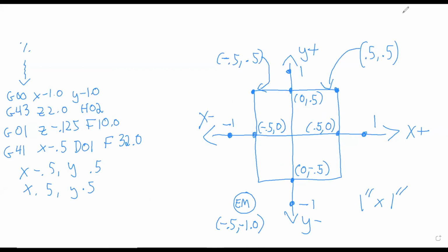All right, so moving forward on using G41 and G42. The last slide mentioned how the machine needs a cutting tool diameter in the diameter value of our offsets page in order to compensate for the tool. But when we call up this diameter, it's going to be just like a G43 code, but with the G41 code.